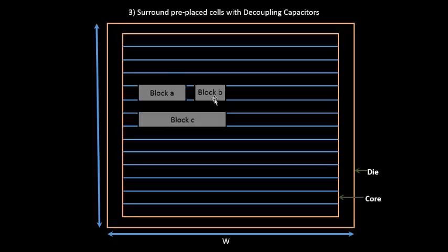So during a finite period of time, let's say this particular block switches at the same instant, and there will be a huge amount of current demand. So this particular power supply, which will be presented in some time from now, should be able to cater to the power needs of these blocks when they are switching from logic 0 to logic 1.